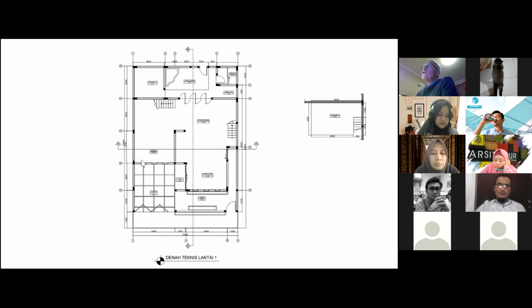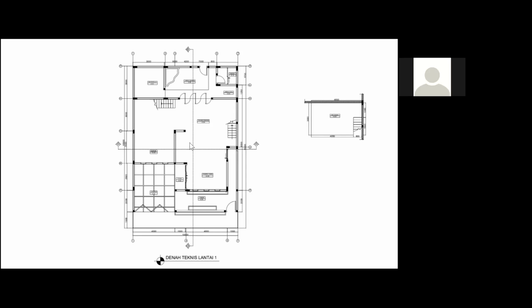If we were using confined masonry construction, these columns don't need to be rectangular. They just need to be practical columns, as part of confined masonry construction. There's no point in having rectangular columns, really, because confined masonry will resist the earthquake forces by forming diagonal compression struts within the masonry. So in the y direction, this house is very strong for earthquake.